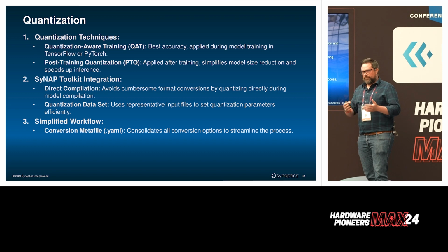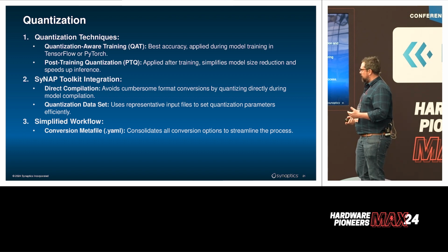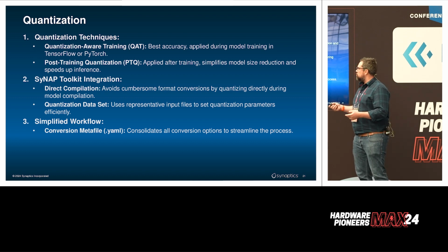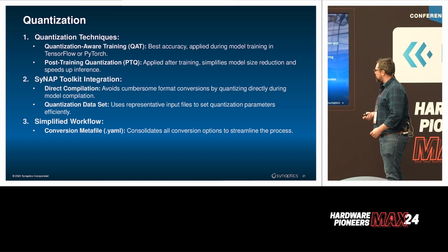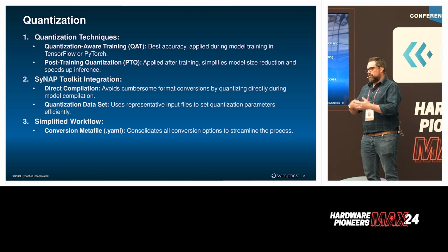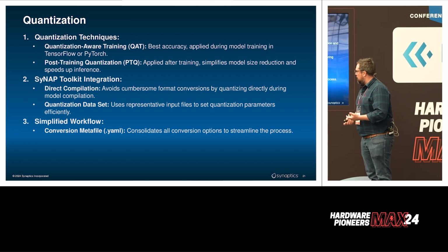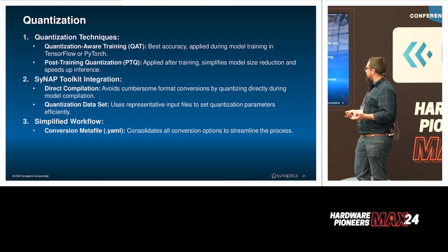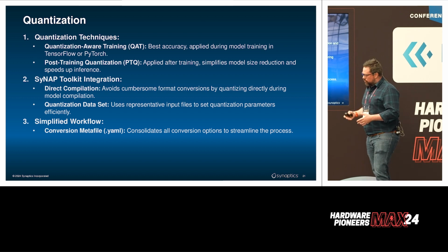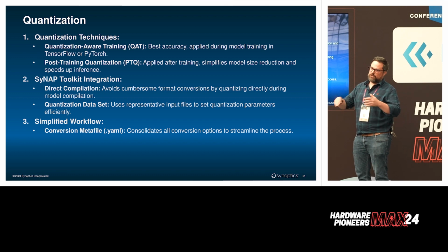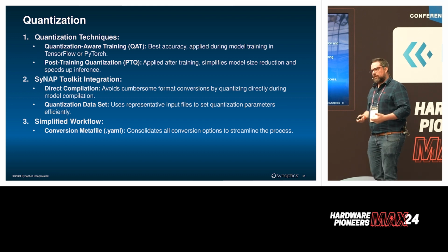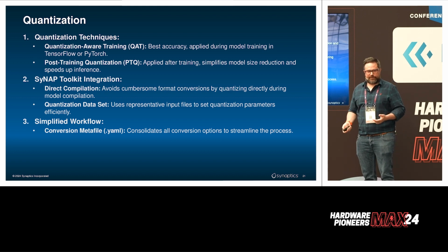So what we developed with Synaptics is using our Synap Toolkit to do the integration. We have direct compilation, just to avoid the format conversion, by quantizing directly during the model compilation. What you need to do is just have a quantization data set, a representative set of input files, to set the quantization parameters efficiently. And what we try to simplify is, instead of having a huge command line to be used, everything is in a meta file. That way you can specify all the conversions that you need for your model.